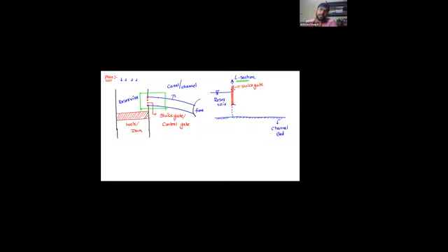When the floods are coming, if there is continuous rainfall or precipitation going on, what happens to the water level? The water level continuously rises, or not? The flow parameters change. Today, the depth of water is one thing, and in the upcoming 2 days, if the rainfall is too heavy, the water level in the reservoir or in the rivers will rise. Today, the depth is different; after 2 days, the depth is different. So is it steady flow or unsteady flow? Unsteady flow. Okay. Now, coming to uniform or non-uniform flow.